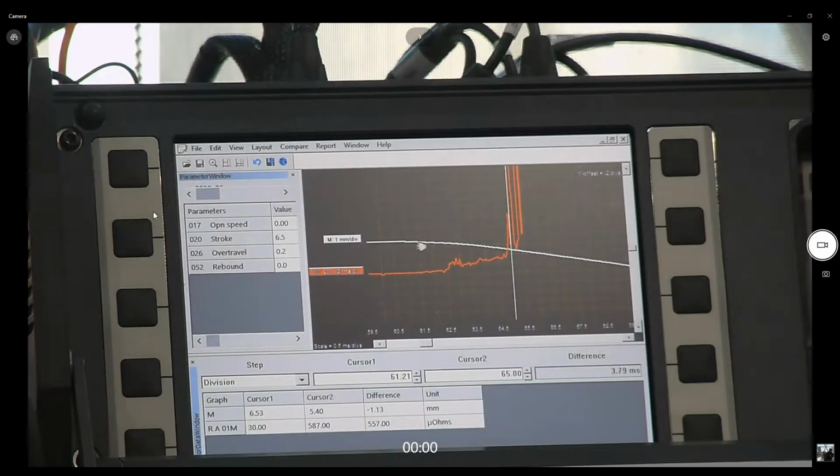We'll take this to the point of the jump. In an SF6 circuit breaker, you will definitely see the jump, but in this type, it will not be as good, as you can see. And then I'll take it to where we get infinity again here. This is one of the circuit breaker poles for you. The motion between cursor 1 and cursor 2 is measured, and the difference is directly shown for you here. 1 millimeter is the measured value of your arcing contact.